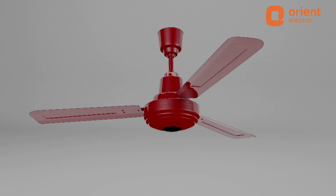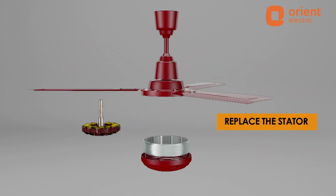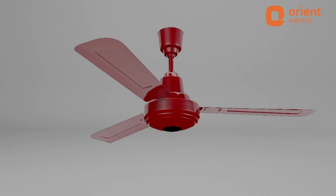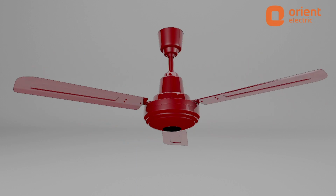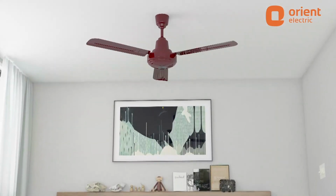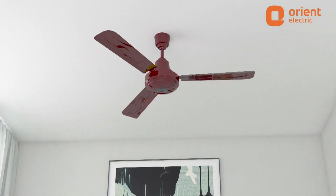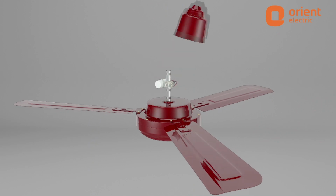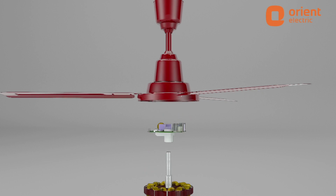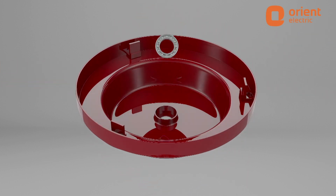A worn-out stator shaft can also lead to a noisy fan, and if that's the case, you simply have to replace the stator. Many times, lack of lubrication in bearing causes a fan to make noises. In such a scenario, first start the fan and run it at full speed. If the problem persists, try re-greasing it. And if the bearing is defective, just replace it.